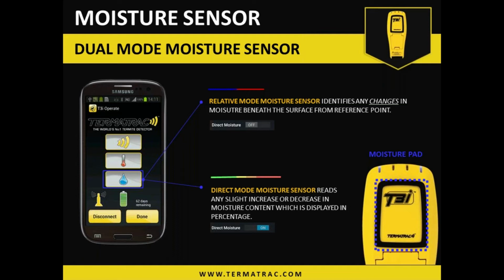Excess moisture for prolonged periods can lead to mold or fungal decay, which is highly conducive to termites. Moisture itself is the attractant to termites, and from that they will generally be foraging closer to where there may be timber products. So having an accurate tool to test for moisture is paramount to a quality inspection. The Termitract offers that within its own moisture sensor.